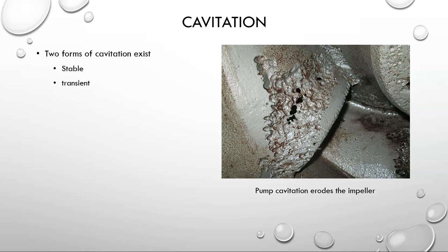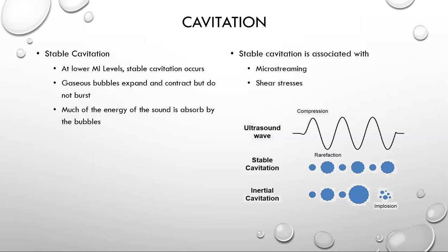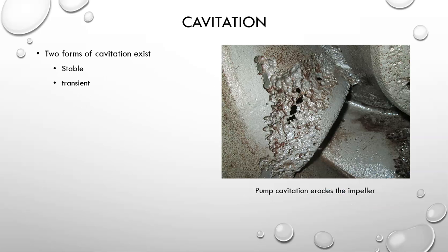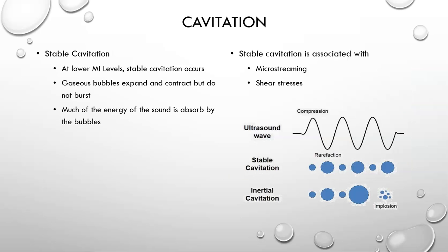Stable cavitation is simply when the bubbles sit there and don't do anything, they don't burst. Just want to go back to that previous picture here real quick. This is what has resulted from transient cavitation hitting this brass impeller. You can see the damage caused by cavitation alone. Anyhow,